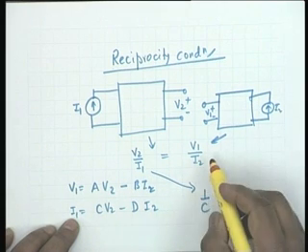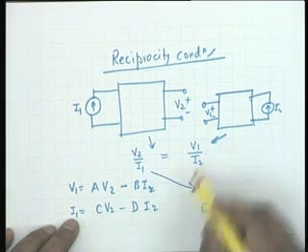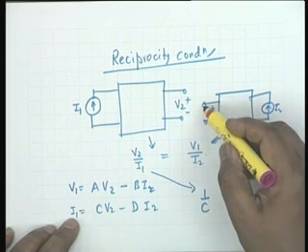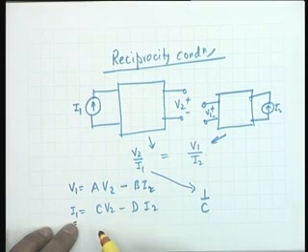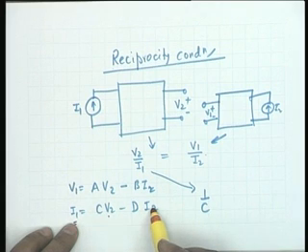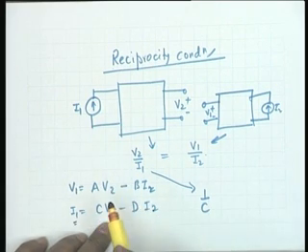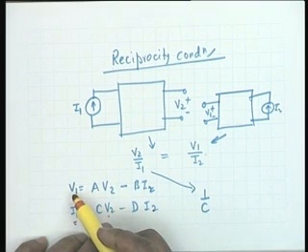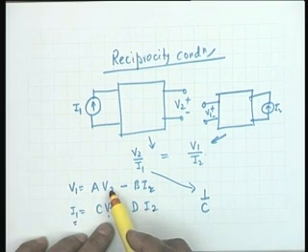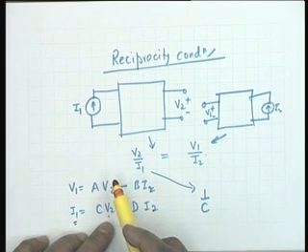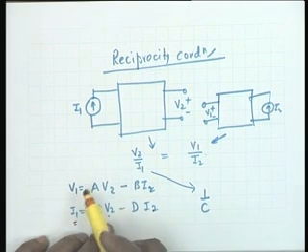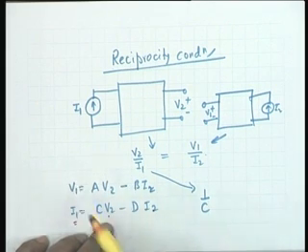What we will do is, for finding out this V1 by I2, we have to put I1 equal to 0. So, if I put I1 equal to 0, I get a relation between V2 and I2, all right. Then in the first equation, you have to find out V1. So, replace V2 in terms of its value in terms of I2, then you can find out V1 by I2.